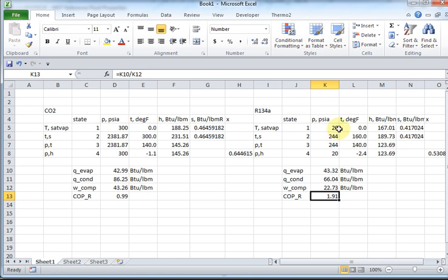Much more reasonable. Let me do this. If I have a leak in the evaporator, the pressure is 20 psi in the evaporator. Is the fluid going to come out or air going to go in? Refrigerant's going to come out. But there's only a 5 psi difference. So it's not going to be a bad leak, you know what I mean? Not like spraying and killing people.